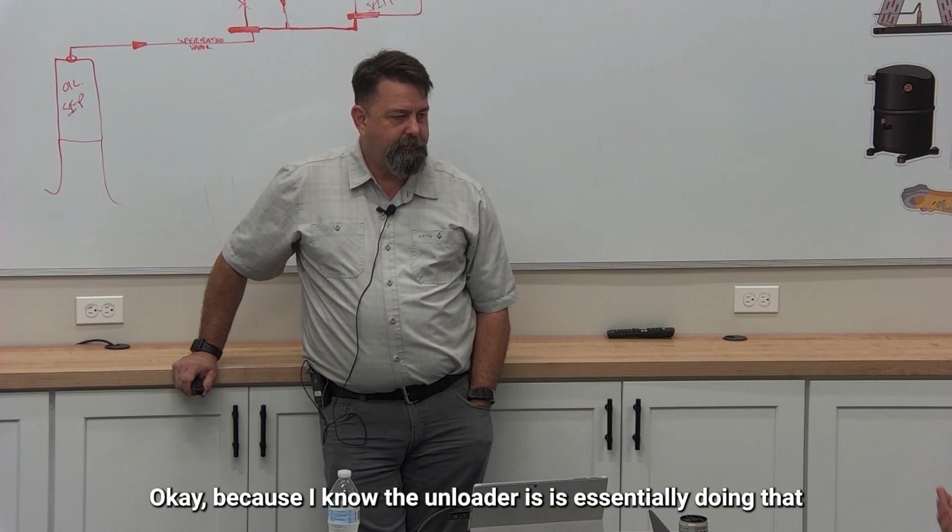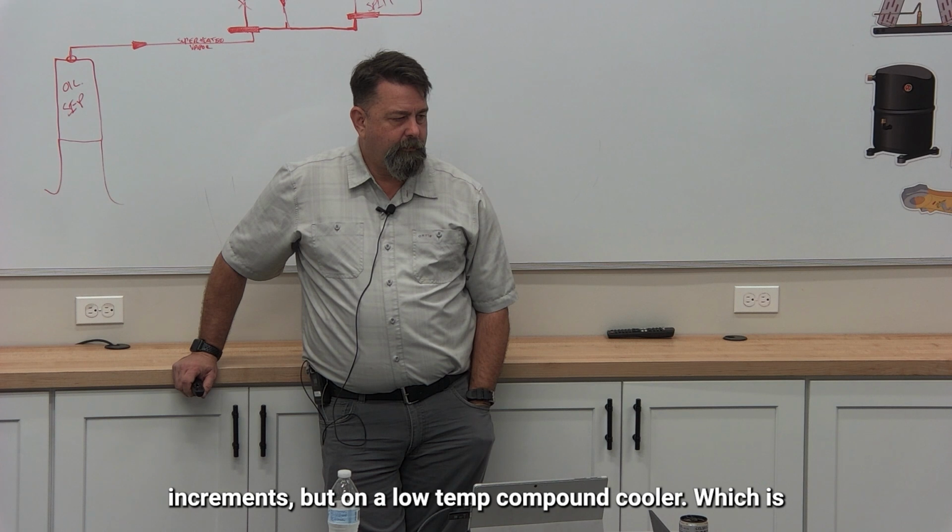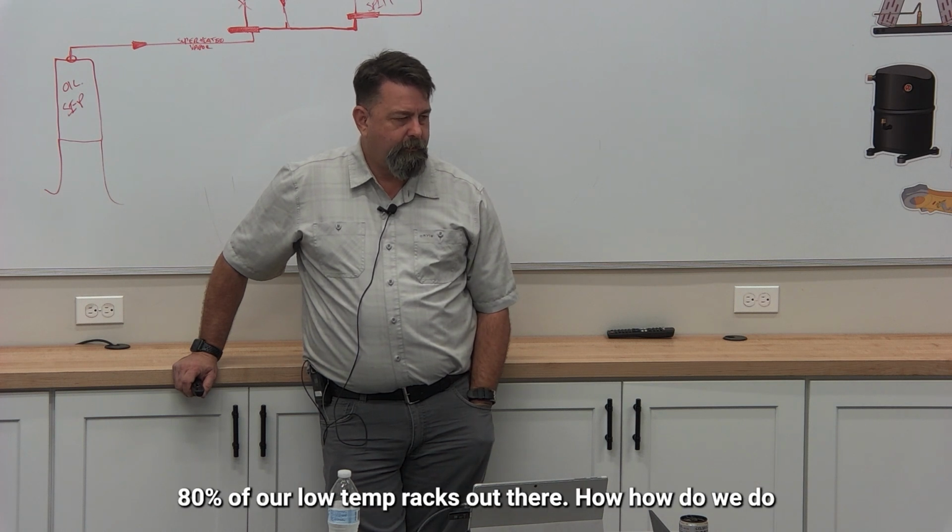Not really. Okay, because I know the unloader is essentially doing that for you, it's stabilizing that suction pressure in smaller increments, but on a low-temp compound cooler, which is 80% of our low-temp racks out there, how do we do that? We just don't. Okay. Yep, that is a downside for compound cooling. Right, that is one of the downsides.